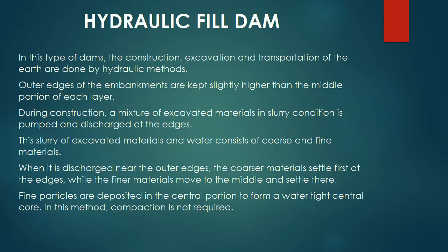In hydraulic fill type dams, the construction, excavation and transportation of the earth are done by hydraulic methods. Outer edges of the embankments are kept slightly higher than the middle portion of each layer. During construction, a mixture of excavated materials in slurry condition is pumped and discharged at the edges. This slurry of excavated materials and water consists of coarse and fine materials.